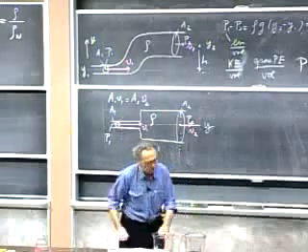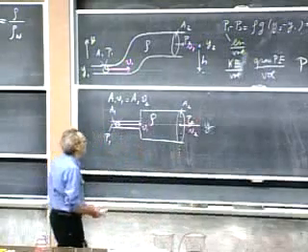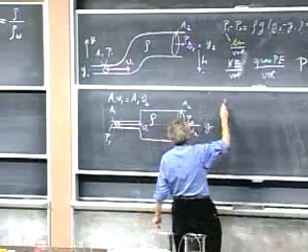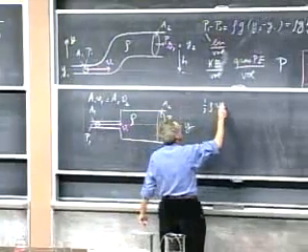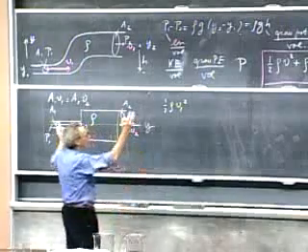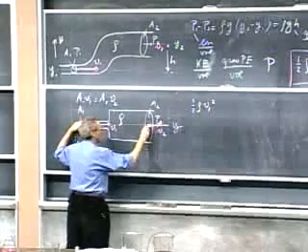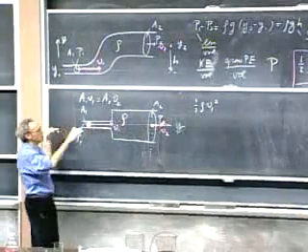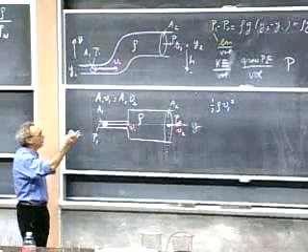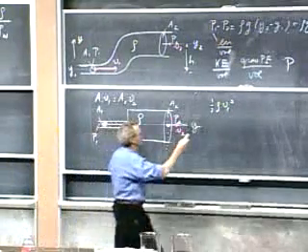Now, I'm going to apply Bernoulli's equation. The first term tells me 1/2 rho V1 squared. I can forget the second term because I get the same term here as there, since the pressure is measured at the same level of y. So I can ignore the second term.